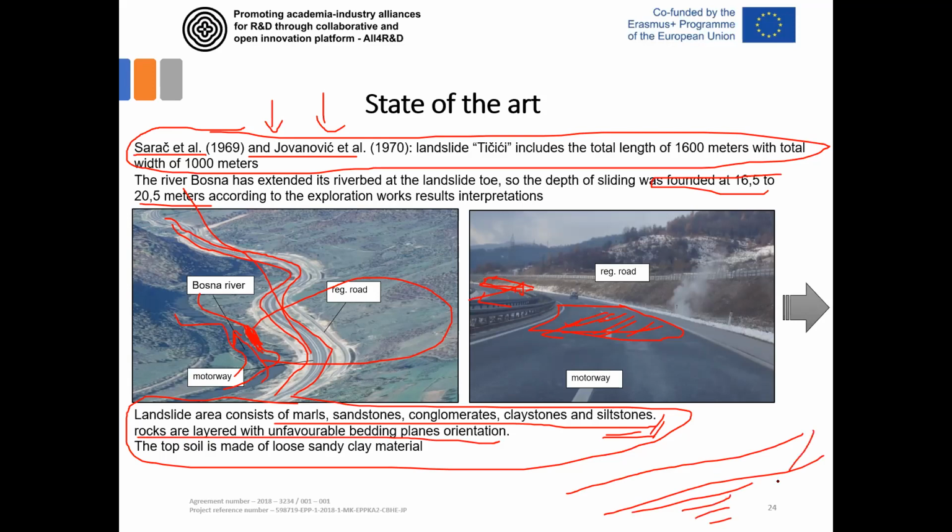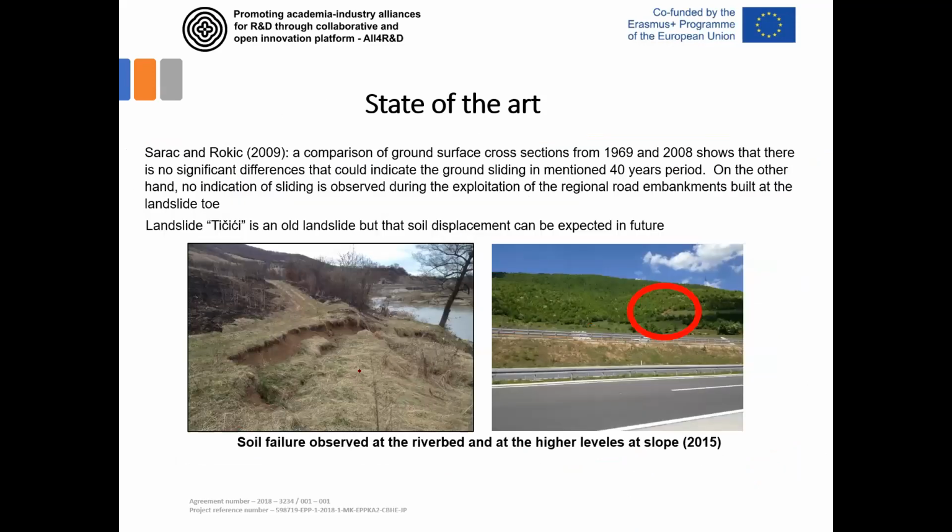So the potential sliding could occur down in the rock material, not only at the contact between the soil-like material and the rock. This topsoil is typically made of sandy clay found near the surface, 2, 3 to 5 meters at the top.